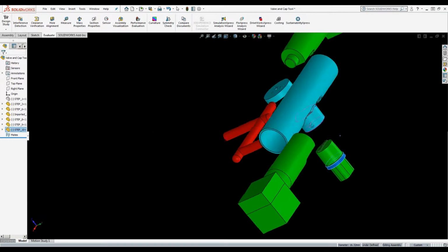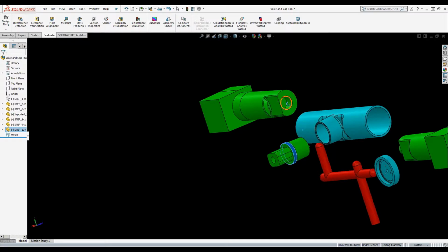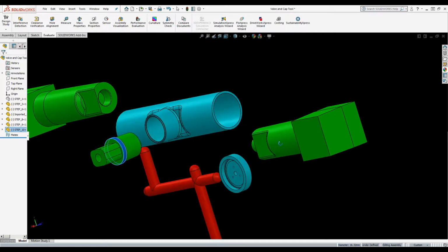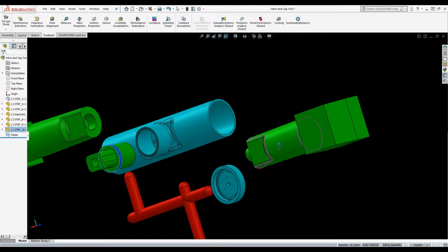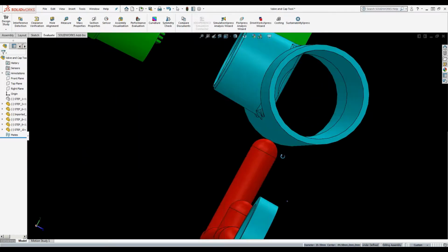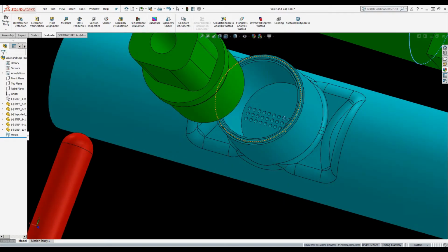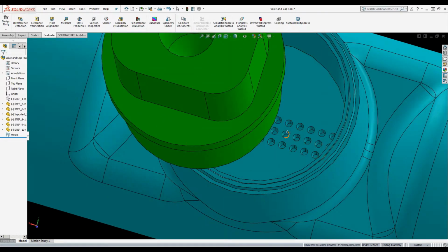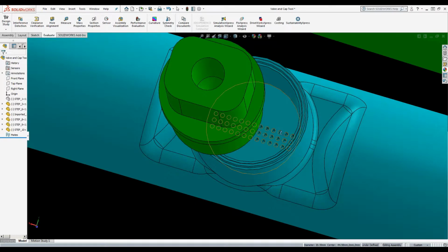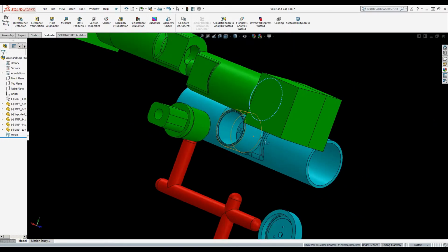You can see the two mating inserts there. Obviously we have a piloted lock to assure that those two are aligned properly during the molding process and they don't shift during injection pressure. That's really the key feature to this part. And again, just adding draft to these types of features, not going zero draft or straight wall, helps with demolding of the part.